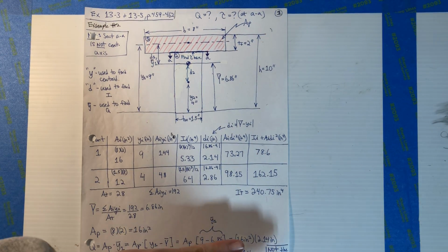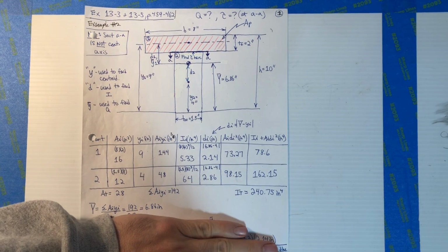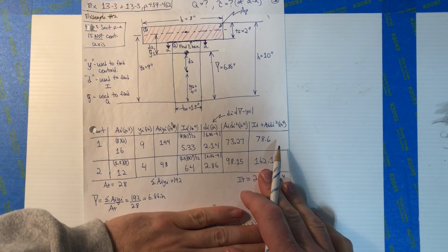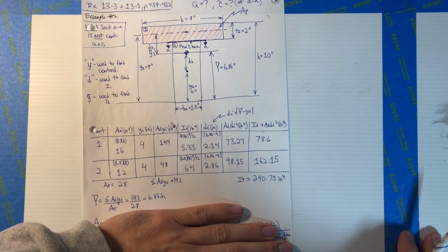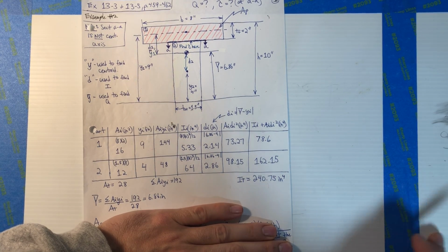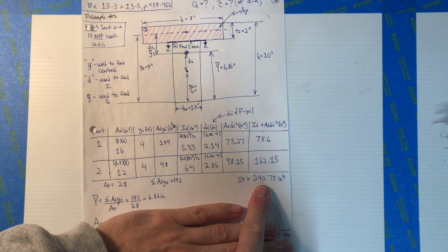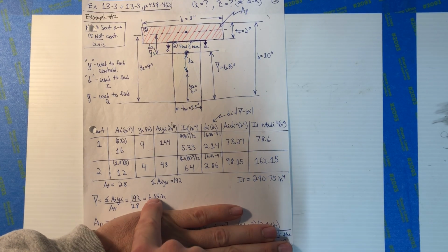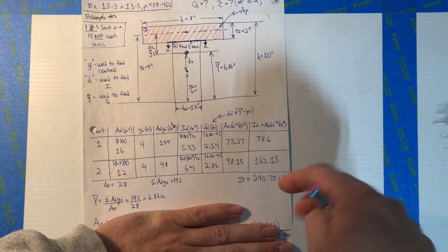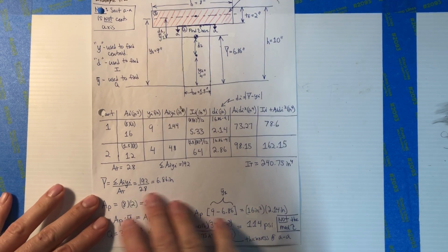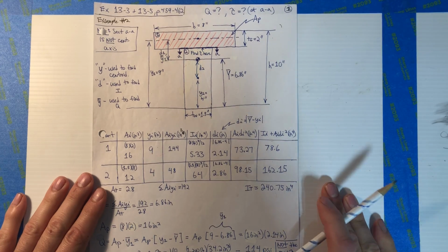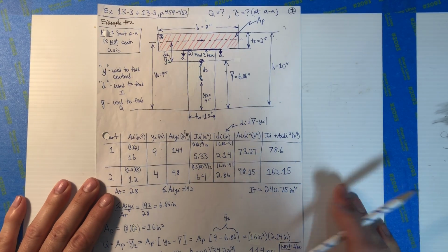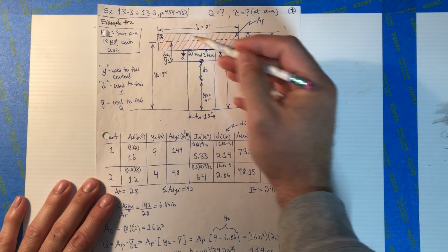So up to down here is exactly what we've done for the entire class. If I gave you this question, I said, hey, find the moment of inertia for that cross-section, you could get up to this point. The first part we did was find the centroid. We find it here. The last part we're doing with the shear stress is really only this added area below. I'm just going to go through this really quickly. So we're going to break up the T section into 2 smaller sections.